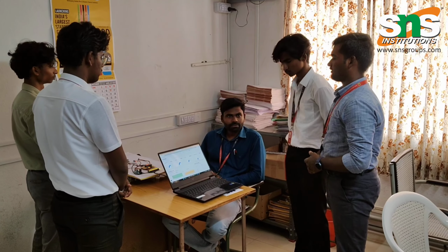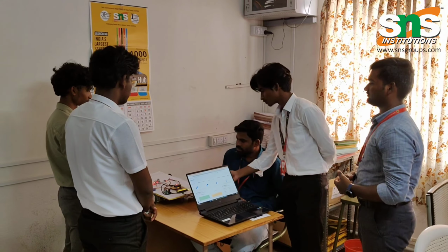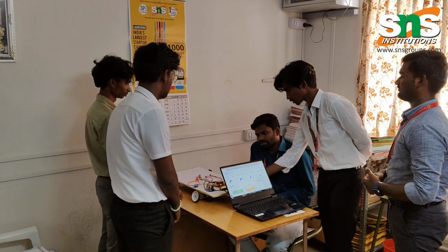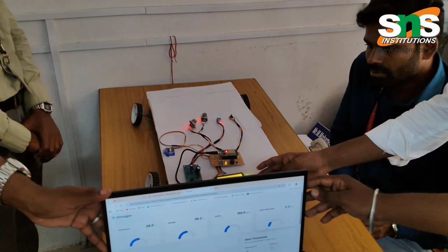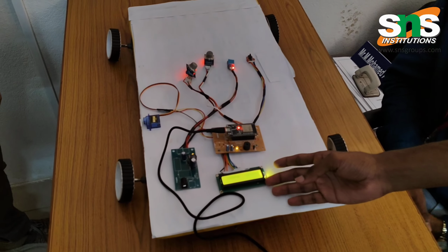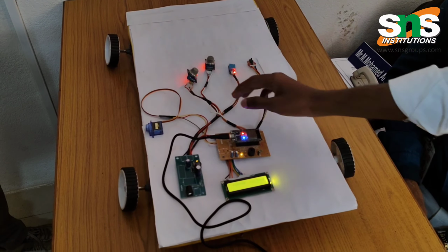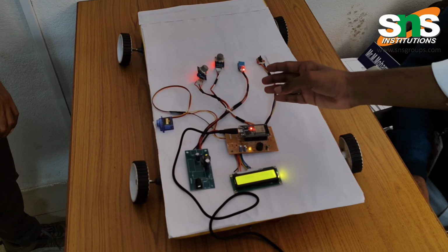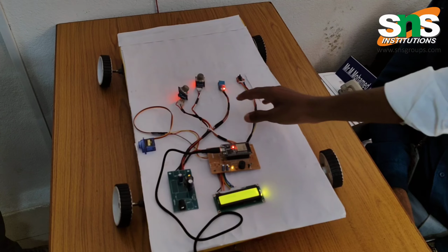Right? So Surya will explain the components used in the system. Here we use the ESP32 to gain the input and control the program, and afterwards we insert the LCD display 2 into 16 for gaining the output results, and a power supply board and two sensors like MQ135 and DHT11 for various gases and temperature.